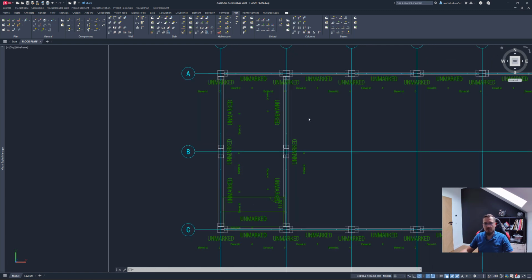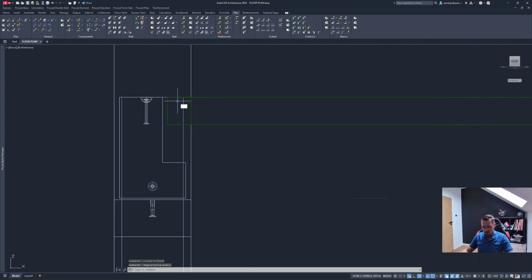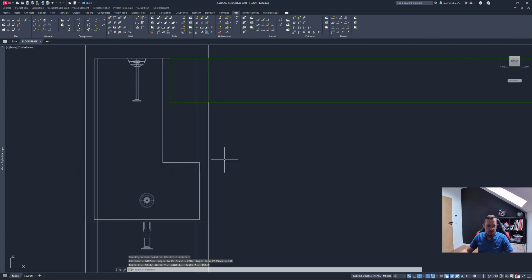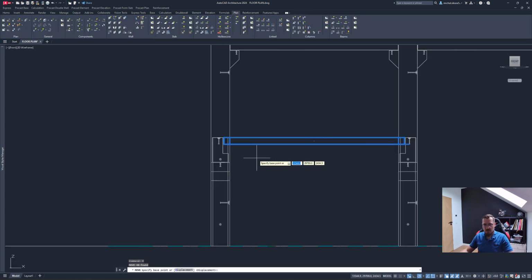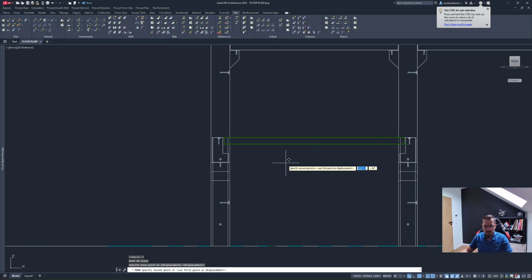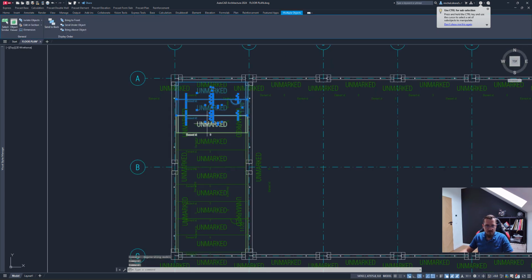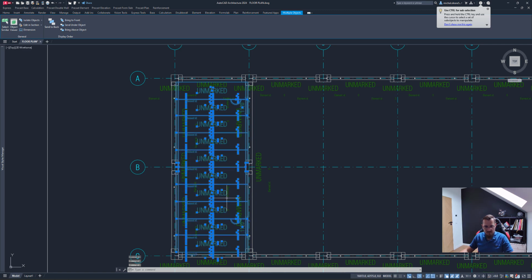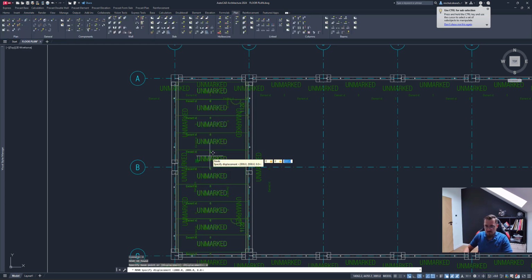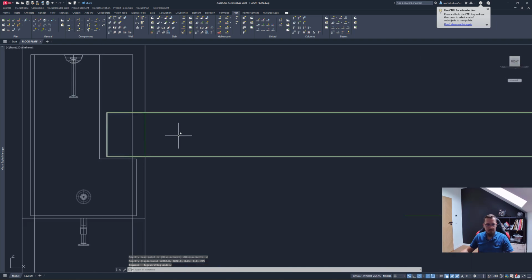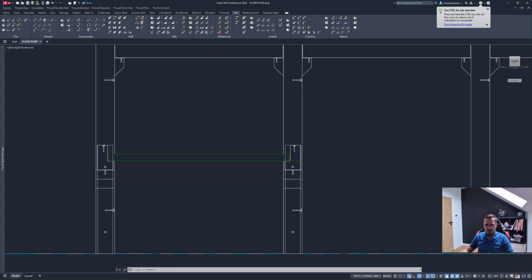Let's verify the front view of the elevation. Yep, so let's just measure the distance for that and lower those hollow cores to fit. That's delta Z is 255, so let's move all the hollow cores by 0, 0 and negative 245. Oops, okay, let's do that from the top view, it'll be easier. That's a bit of a skill issue for me here. Okay, displacement 0, 0, negative 245. Yep, and now let's verify. Yep, that's perfect. That's the way I wanted that to work for this ledge columns.